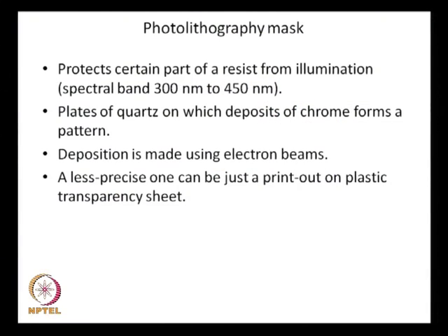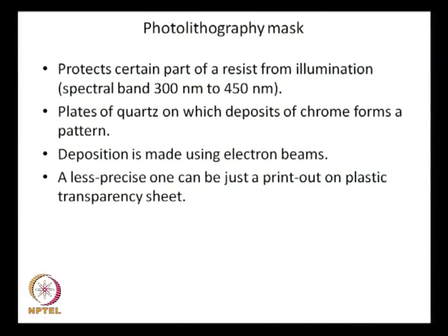However, there are alternative routes people are looking for, and the photolithography technique is one such method which has been borrowed from semiconductor fabrication processes. The method has been tailored for fabrication of microscale devices. So, the essence of this technique has been taken from semiconductor manufacturing. However, the technique has been tailored for the fabrication of microscale devices. Now, we need to discuss first how this photolithography works.